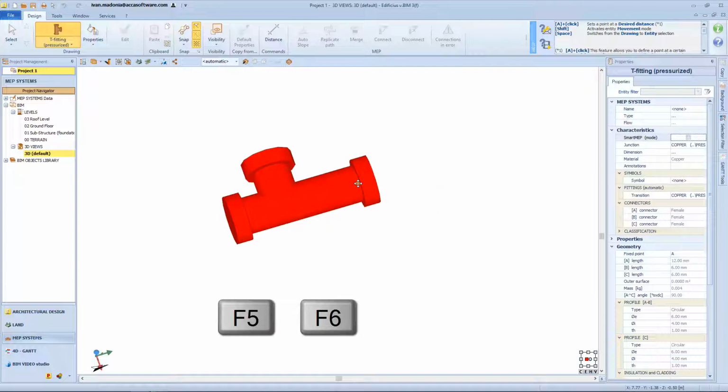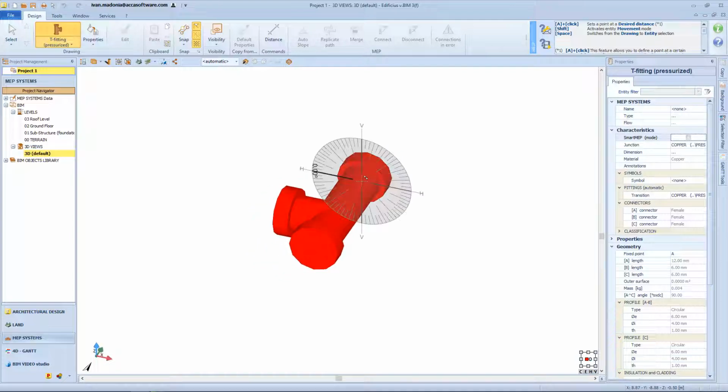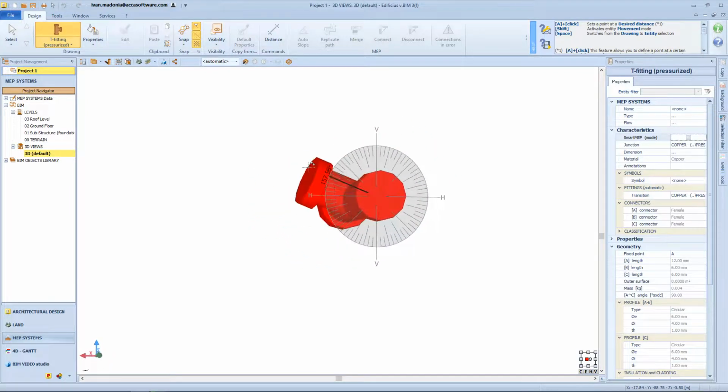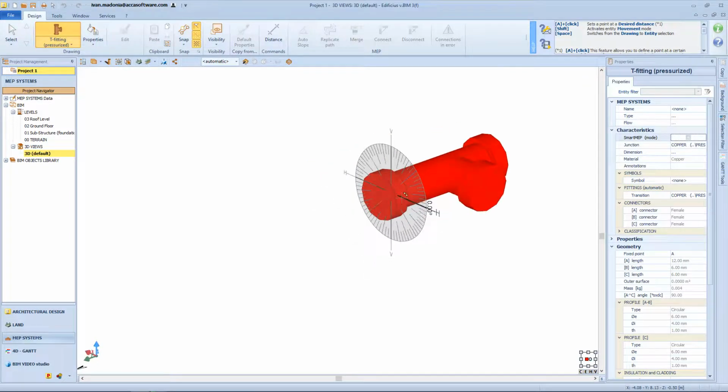With a second click, the junction is set into position and, in the case of the T-junction, if the mouse cursor is linked to the connection port, a protractor appears at port C, and can be used to define its rotation angle, similarly to pipes with the directional cube. In general, for fittings you can graphically define the rotation angle of a branched section in 3D space.